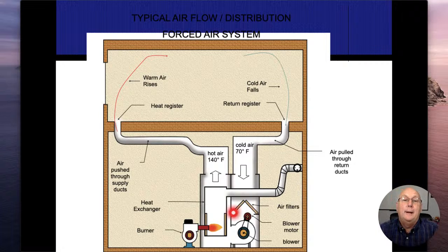All right. And then if we think about it, even if I had a hole in my heat exchanger, because now this is under zero pressure because I do not have an inducer fan. If I had an inducer fan, I would create a negative pressure inside here, and then I would also have a positive pressure being created on the outside of the heat exchanger. If I did have a hole or crack or opening in there, that means that the air would be flowing into the heat exchanger instead of allowing gases to escape. Please don't take what I just said as me saying that it's okay to have a hole or a crack in the heat exchanger. It is not, by any means.